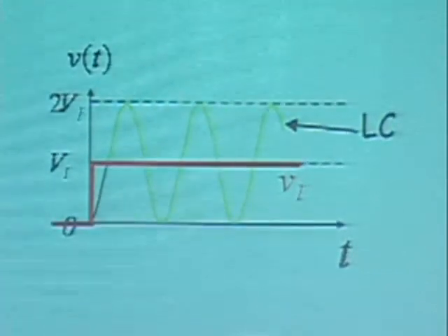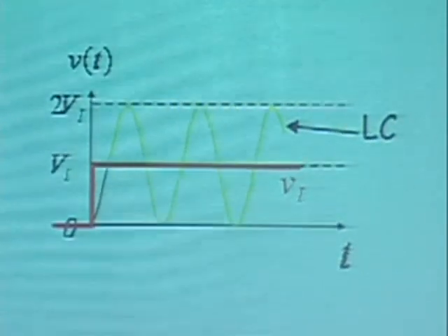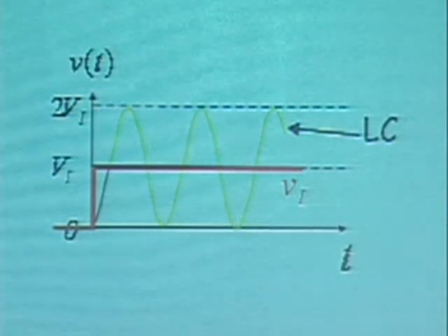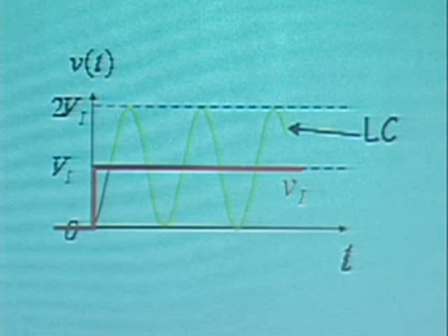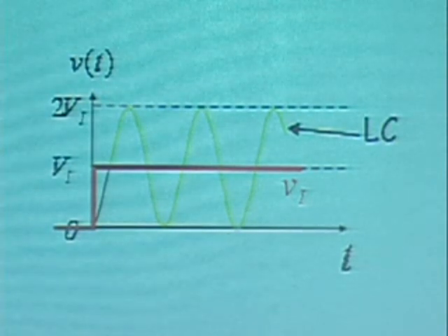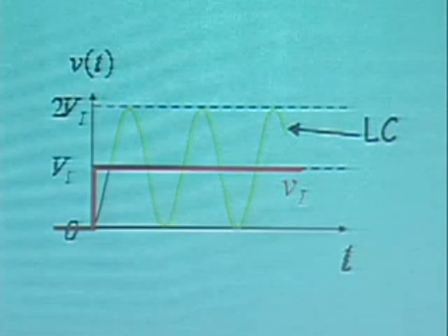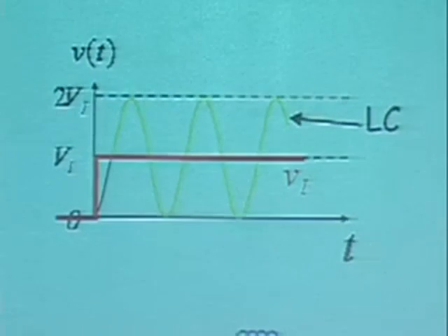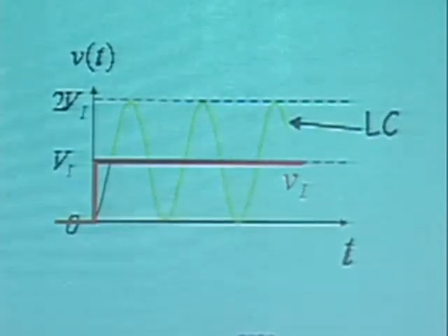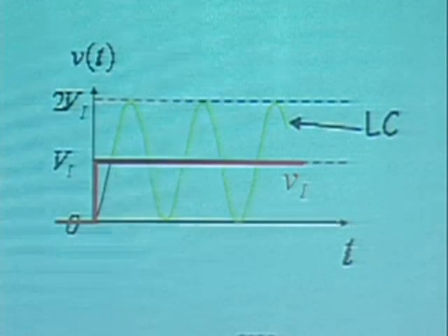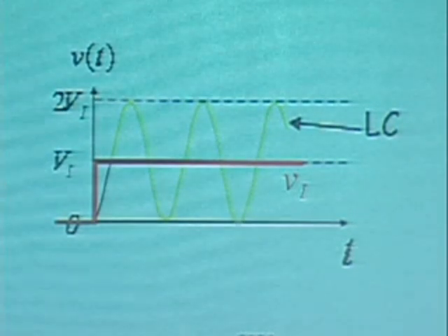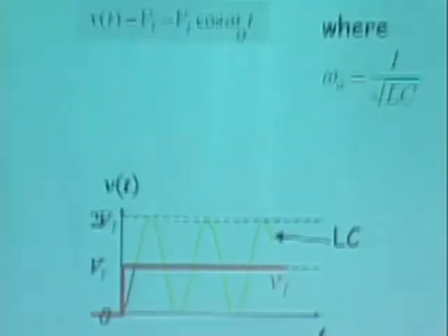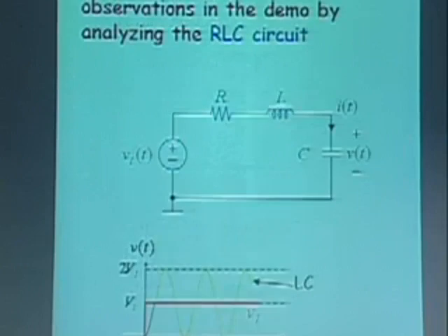Let's say you have a 1.5 volt battery, a AA battery, but let's say a circuit needs 1.8 volts. The Pentium 3s, for example, needed 1.8 volts. The StrongARM is another chip that required 1.8 volts a few years ago, but the AA cell was 1.5 volts. How do you get 1.8 from 1.5? Well, you have to step it up somehow. And this basic principle where the voltage can jump up above the input is actually used, of course, with additional circuitry, to get higher voltages. It's a really key point that you can squirrel away. So this was pretty much where we got to in the last lecture.